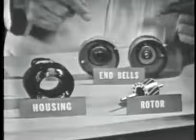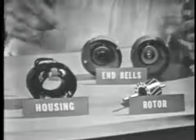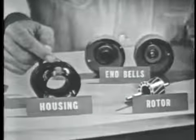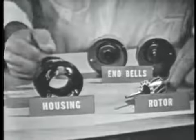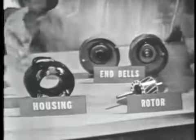A, the end bells. Remember, they just hold the bearings for the motor. B is the housing and the stator windings. Very simple and very rugged. And C, of course, is the rotor. Right now, there are no slip rings or wire windings. And of course, overall construction is very simple, very rugged.